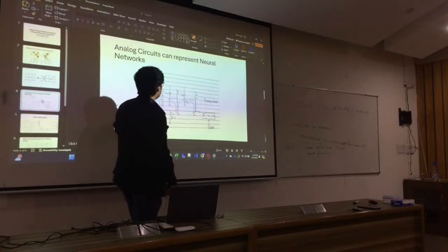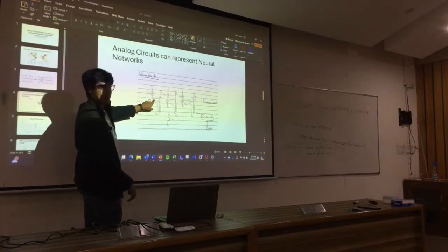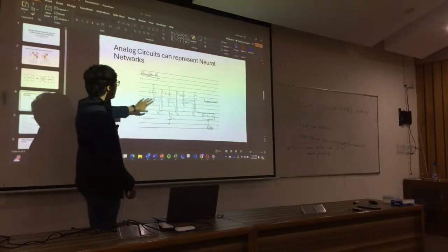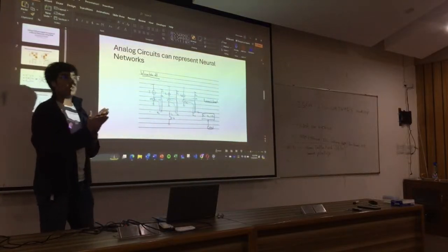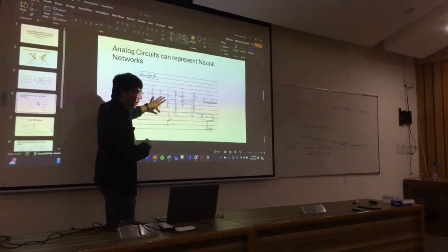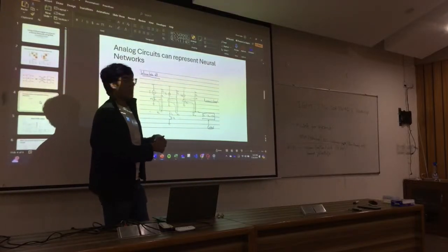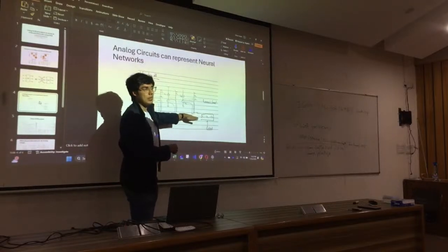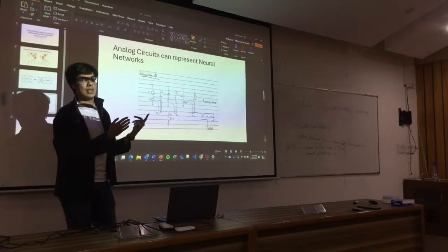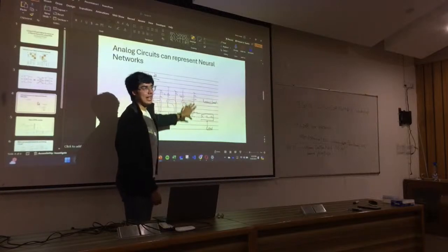What would take place is that each of these inputs is biasing this transistor. And they're all connected to the same voltage gate. So the smallest current would bias the corresponding transistor the least, and is the most likely to switch off because they are all being held to the same reference value. So only the transistor corresponding to the largest current would switch on, and every other transistor would switch off. Winner takes all. The largest current takes all.